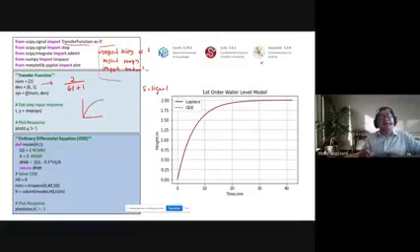In this case, step the system, and you will get something like this. In this case it's the blue color, and if you look here there's an overlap. It's a Laplace in the blue color. The code is evaluated line by line. The green color is the comment, so the compiler will not evaluate the comment line. I call this step, and step will give output in terms of t, the time x axis, and y, the y axis.